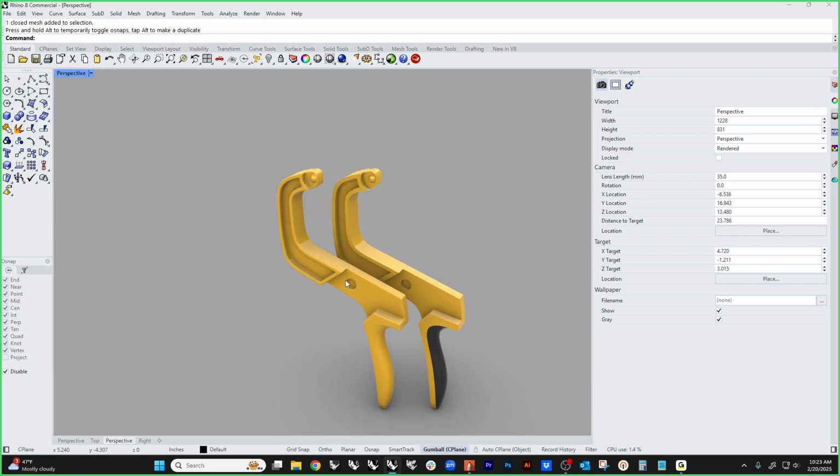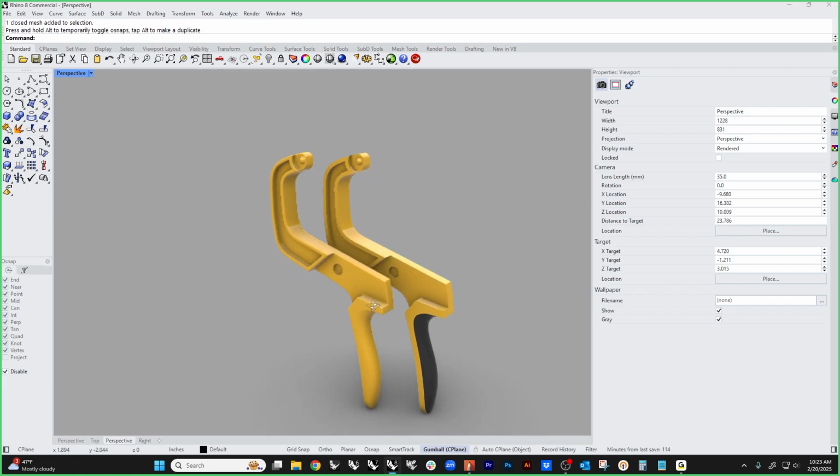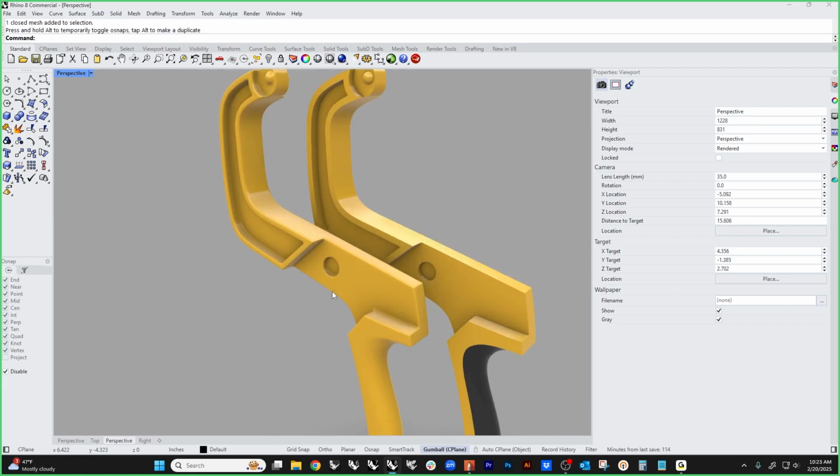I use this all the time if I just need to knock the edges off of everything. And like I said, if you need sharpness in other places, save some cutters. So I would save a cutter that would make this hole, and I'd probably save a cutter that makes this edge down here. Shrink wrap the part first and then do a mesh Boolean later, and then you get a really sharp edge with the softness everywhere else.